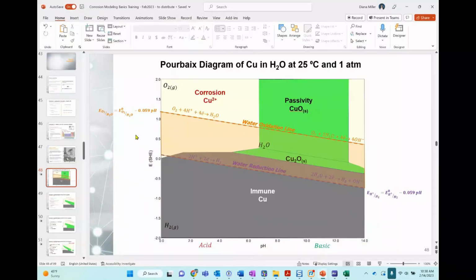In the lab, you can use what we call a potentiostat. And literally what it does is just puts up and down these potentials. You say, I want my system to be at this potential, and it applies some current and makes sure that you are at this potential. That's one. That's in the lab. In real life, there is something called impressed current. This is for pipelines, to cathodically protect them. They also pass a huge current, and that is going to make the potential lower. That's another one.